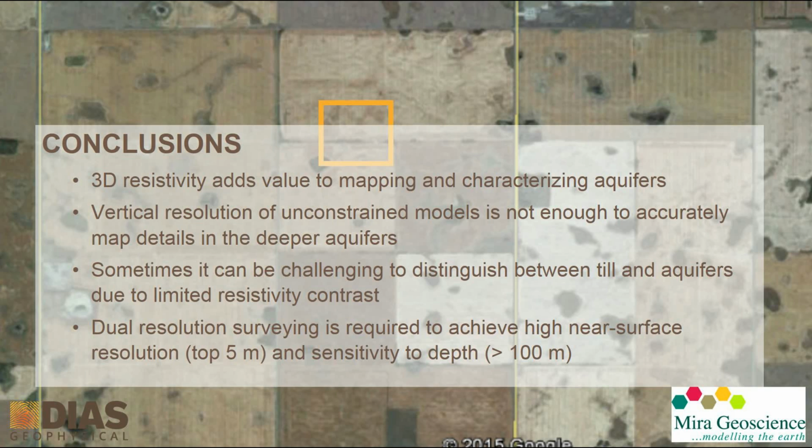So where your dipole is running along a voltage equipotential, you have extremely high error in your resistivity calculation, or voltage, depending on what you're using. So as a result, those readings are unreliable and should not be used in the inversion process.